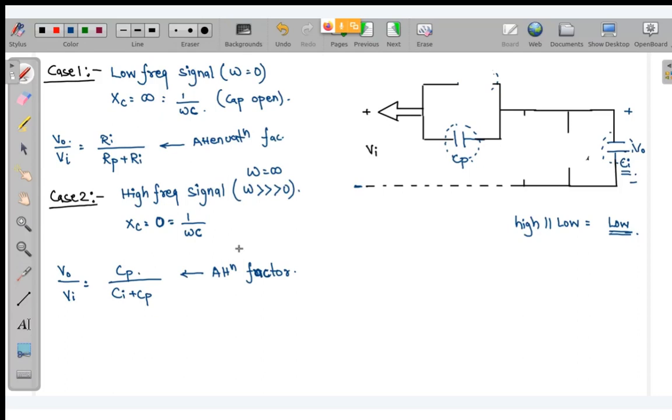This is not a filter. Okay, this circuit is not a filter. You could have said, yes sir, we have one circuit where we have different attenuation at different frequency. For example, a low pass filter. Okay, this is the magnitude and this is your frequency. So this is your cutoff frequency. If this is A, this is A by root 2 magnitude of the signal. So you can say, sir, different magnitudes of a signal or different attenuation we have at different frequency.